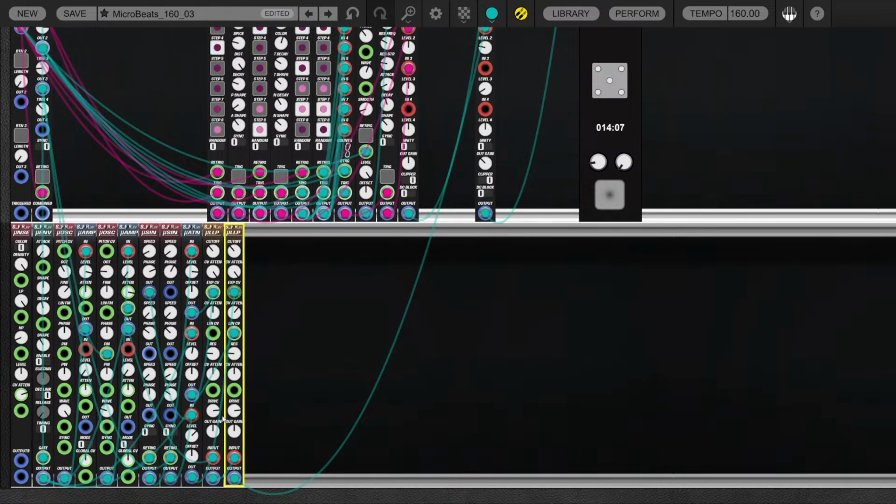It will go out of tune with heavy resonance and heavy drive, but it is pretty stable. Linear FM, or the linear cutoff CV in that case, will offset the cutoff frequency linearly. So it will not follow the pitch scale. If you offset it 10 Hz, it'll be 10 Hz.